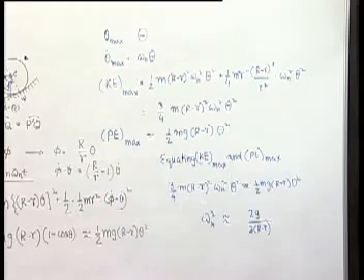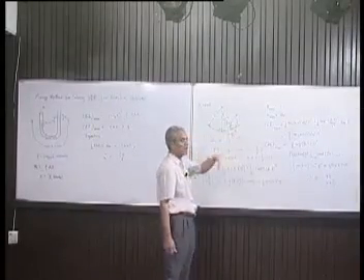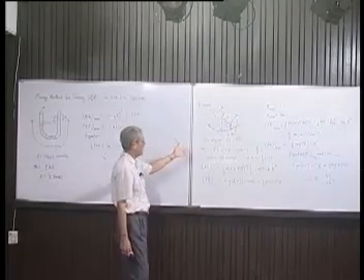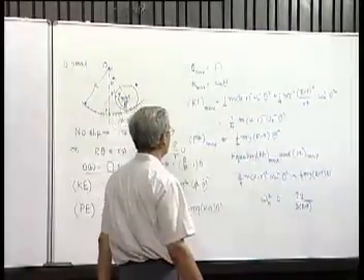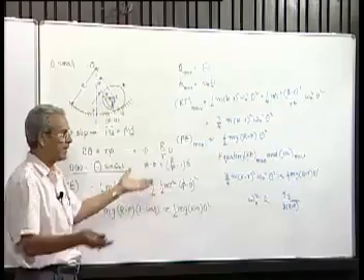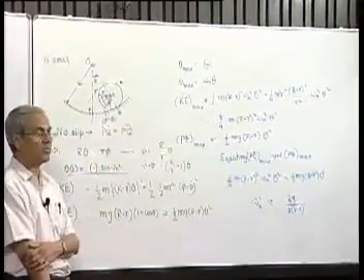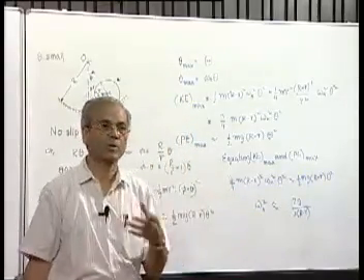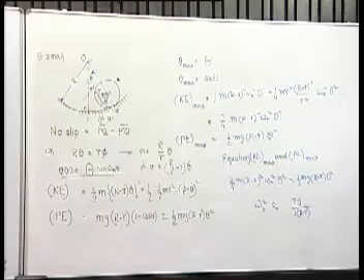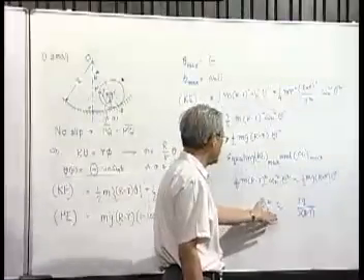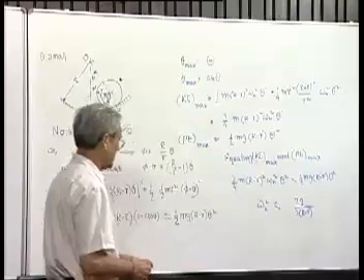So here we find that the problem, if we try to solve using the Newtonian approach, will be very difficult. We have taken the energy approach, where of course the conservation principle has been used. We could also add the two and differentiate with respect to time and get a differential equation in theta, solving which we could get the same natural frequency. On the other hand, we have assumed that all small oscillations are simple harmonic functions of time, and by equating the maximum kinetic energy with maximum potential energy, we get an algebraic equation for the natural frequency, which gives the result like this.